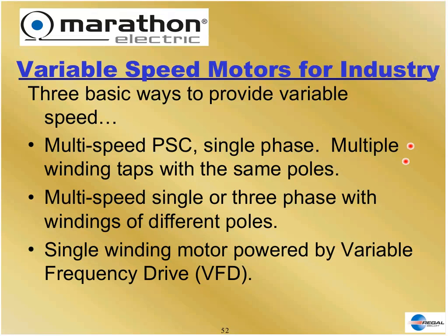But I have three kind of distinct speeds there. The other thing, the second factor, is the number of poles. I can change the number of poles. I can put in a 4-pole motor and an 8-pole motor. Now I'll have two speeds.